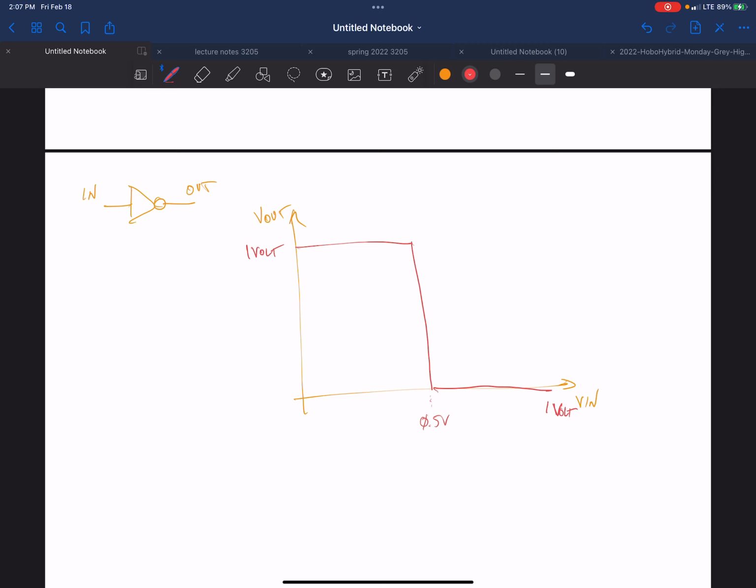But this is the next thing that's really nice about the CMOS logic family. Again, now we only have that to pick from, so we don't know how bad things were before. But because of this pull-down, pull-up network, when you are passing a 1 or a high supply through, after you charge your capacitor up, there are no resistive dividers, right?